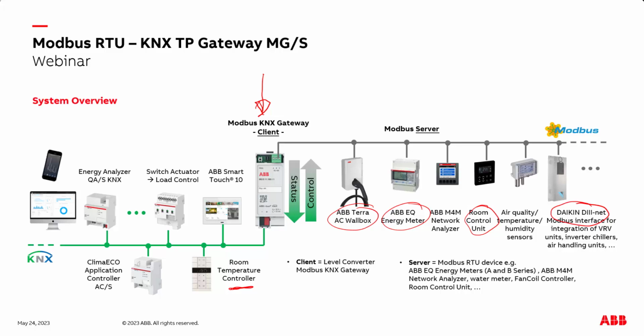Do not forget our wording. Our gateway is the client, our so-called level converter, and on the right side, in the Modbus world, we have only server devices, which answer the requests or the polling from our client.